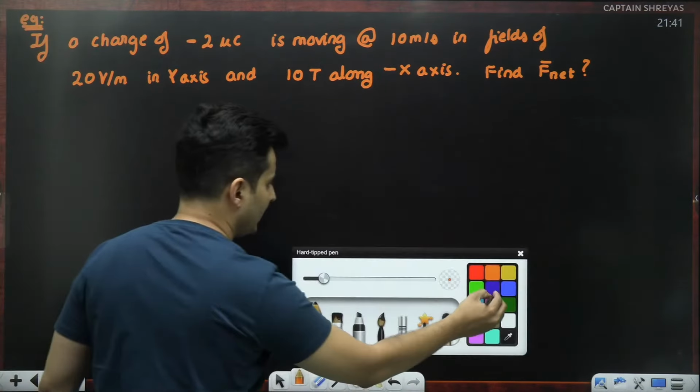Okay, very, very important, guys. The motion of such a thing is basically a helix. Helical motion. After one revolution, if you notice, if it started from here, it came here. Again, after one revolution, it came here. The distance between those two points after one revolution is also called the pitch. Pitch means in one revolution, how much do you go ahead? That pitch can be calculated easily, not that difficult.